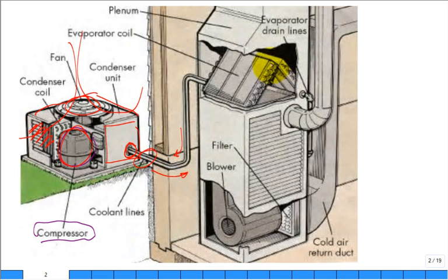And then up here they have an evaporator. They have it usually sloped such that when you draw hot, humid air across that cool evaporator coil, you'll get some condensation on the outside of that coil, and that will then drain, that liquid water will drain down into a little catch pan on the sides, and then they'll drain that condensate out of the house. They may just dump it outside, they may dump it down a sink, but they need to get it where it's safely disposed.